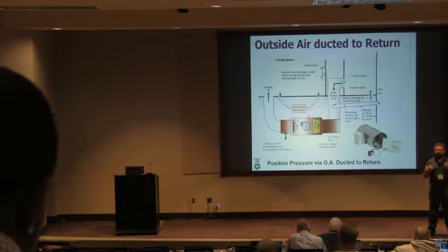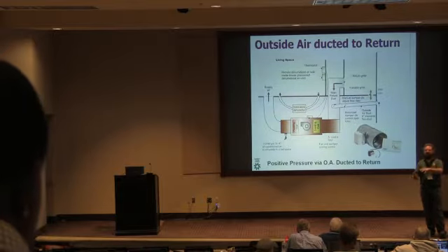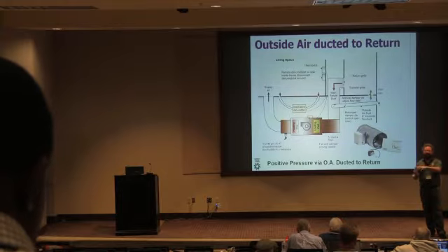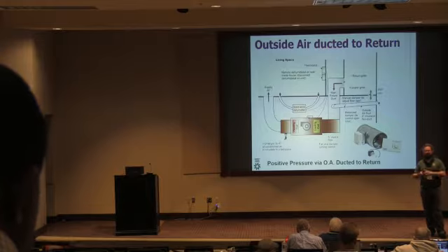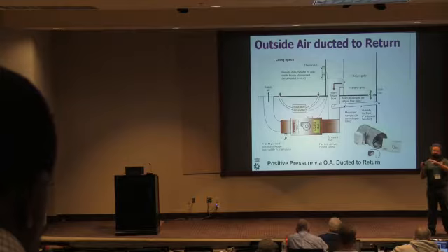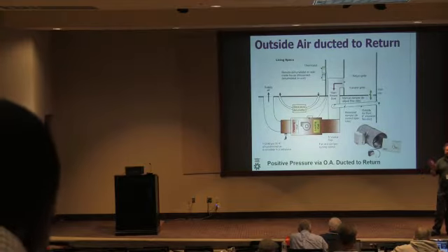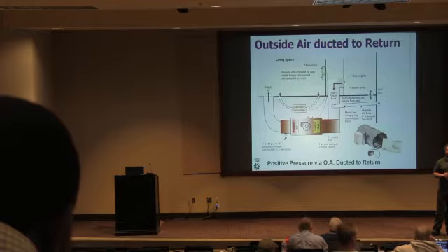Again, I would put it on both systems, but I think someone could make the case that they were going to take the primary system for the home and do all of the ventilation on that system, and it'd be hard to tell them that's wrong as long as they're meeting the required volume CFM. I would put it on both systems, but I think you have a hard time telling someone who can meet the required rate with just one system that they're not meeting the requirement.